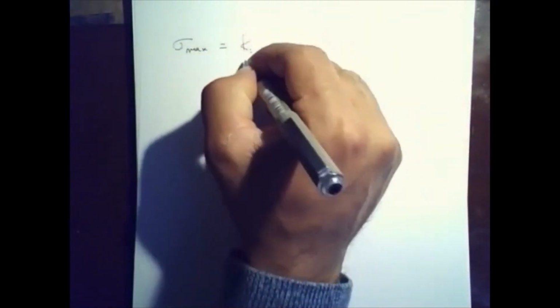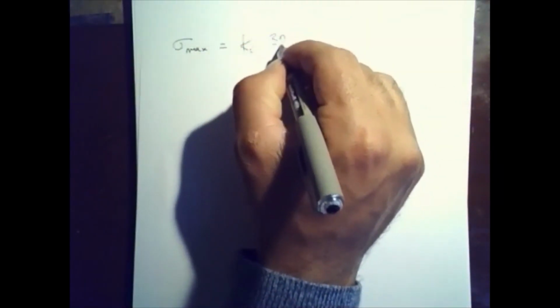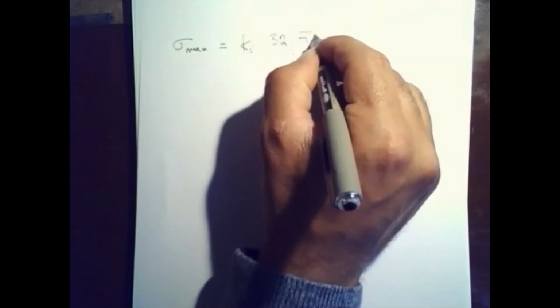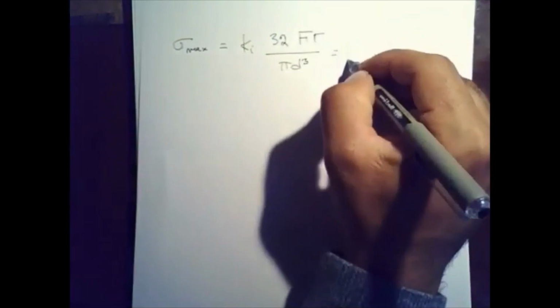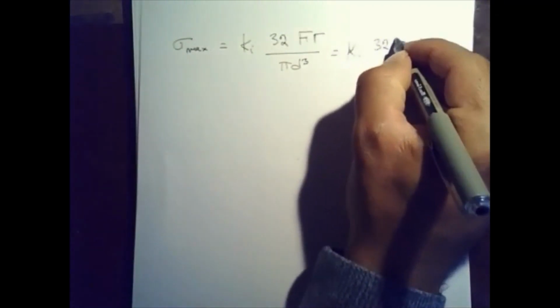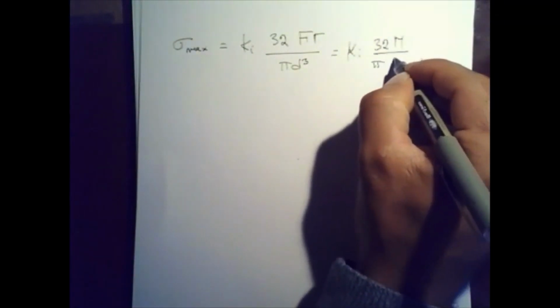What I would like to also include is, so right now we have the bending moment, right? Like I said, the maximum bending moment on a torsion spring is going to occur on the inner fiber, and that is going to be equal to 32 FR divided by pi d cube, which is essentially 32 times the bending moment, right, which is happening on the wire.